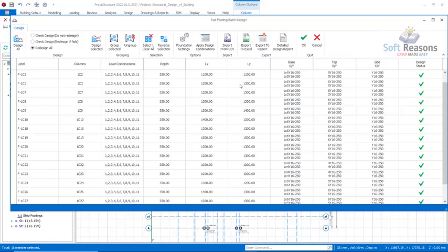So you now have to interact. If you want it to be square, this one is 1.1. This is supposed to be 1.3 by 1.3. This is also supposed to be 1.3 by 1.3. You can see 1.3 by 1.3 being repeated. So for it to be repeated just like this, you can consider grouping. You can group select it.